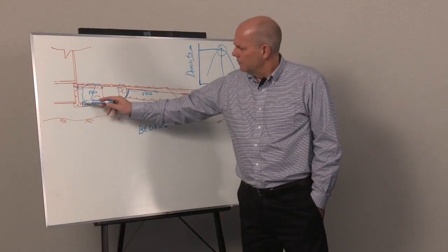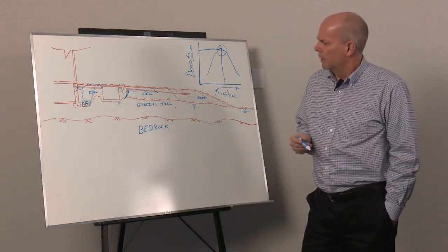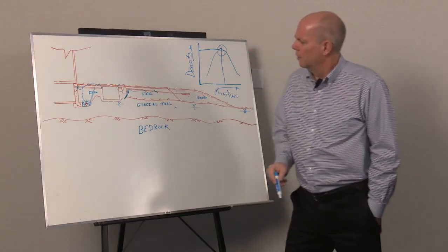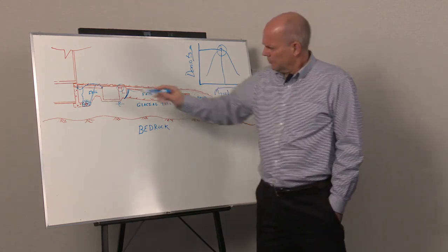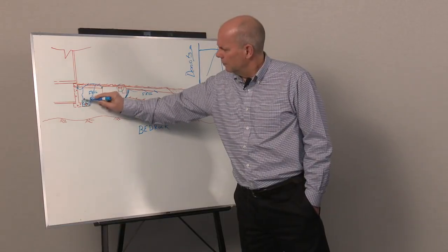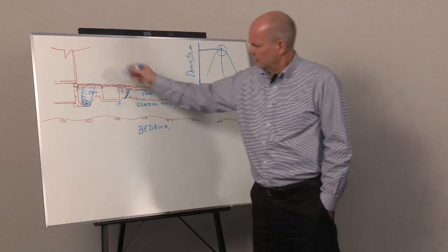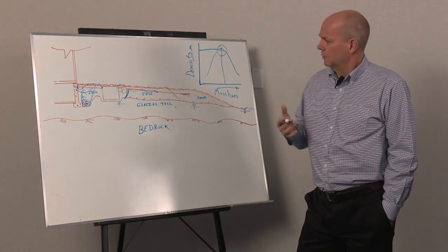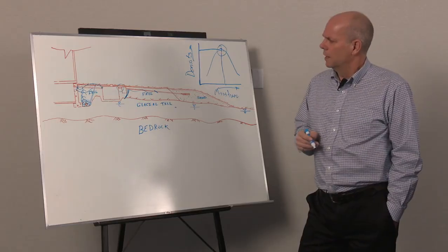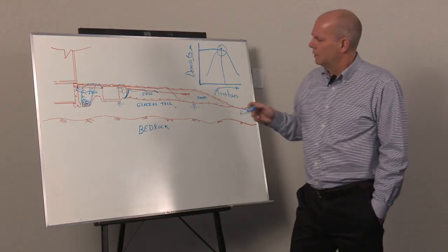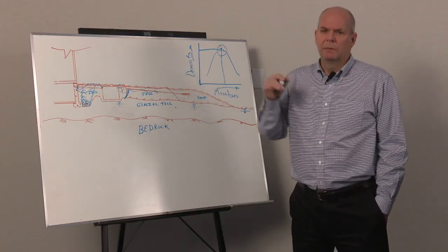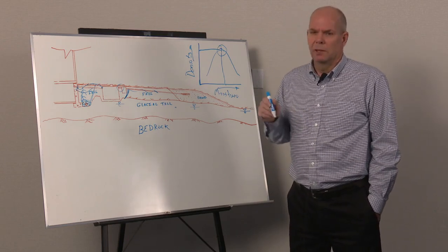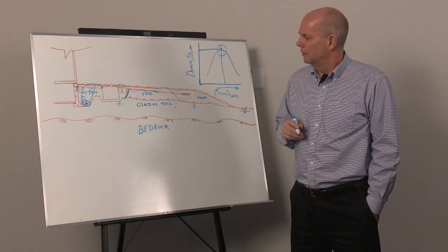Another thing that can happen sometimes is if this gravel layer is not properly wrapped with geotextile and you've got groundwater constantly running in there, surface water, drainage from the roof drains coming in there, you can start to lose material washing into this gravel layer, and that can work into a settlement trough up at the surface. That's fairly common to see, settlement from just the fill itself, but you can also get it from loss of fines into that clear stone. Anytime you're putting in clear stone around a building that's going to be backfilled on top with a fine-grained material, you have to have the geotextile there, or you run the risk of losing a lot of your fines into the gravel and pipe.